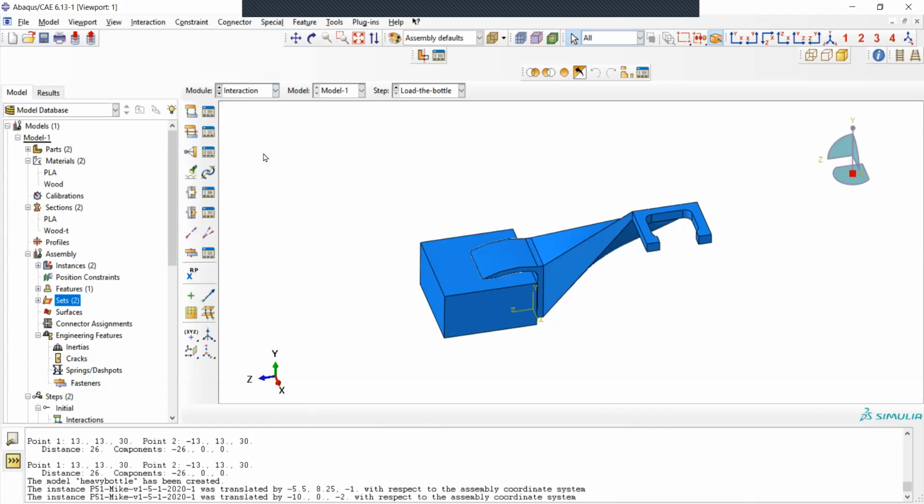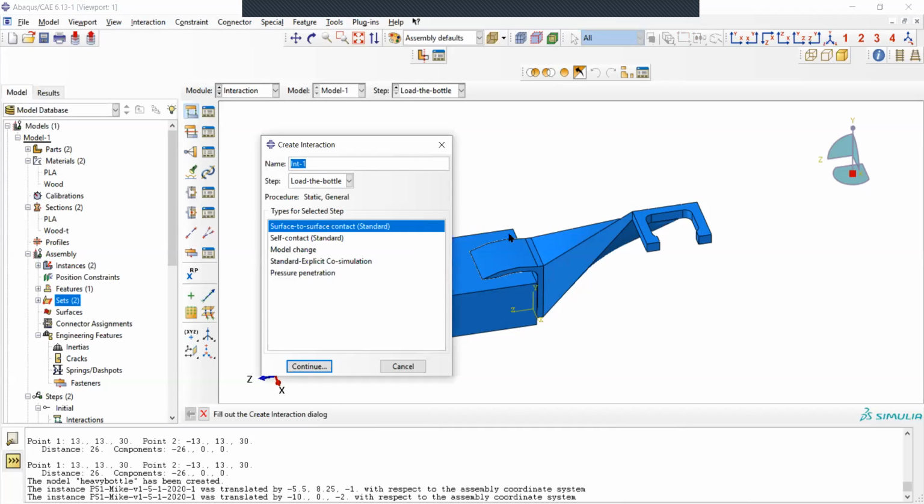We go to interaction. So this is again important. In our case, we need to have friction between the table and the part. Again, you follow this list and you can always check on it here. Whatever you see here is not necessary for basic mode or for whatever we're doing now. This is advanced. So we stick with those. We start with the create interaction. So we want to create an interaction between the parts.